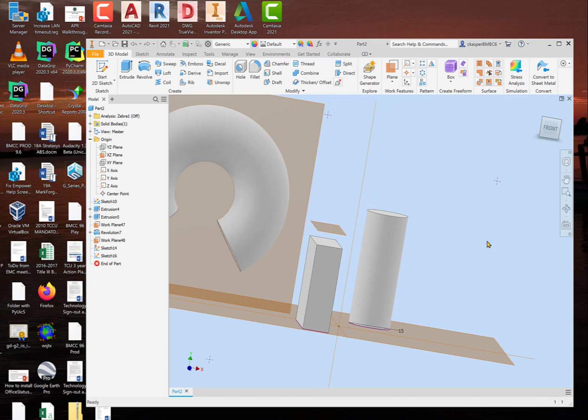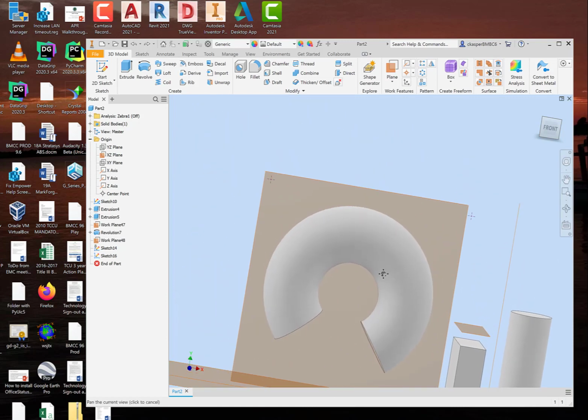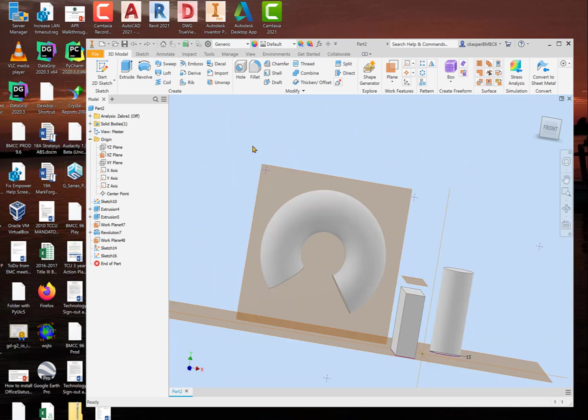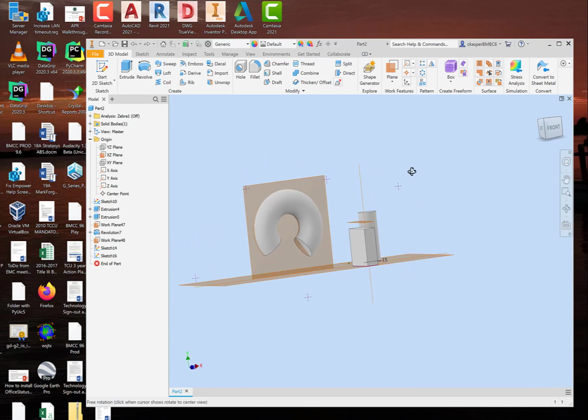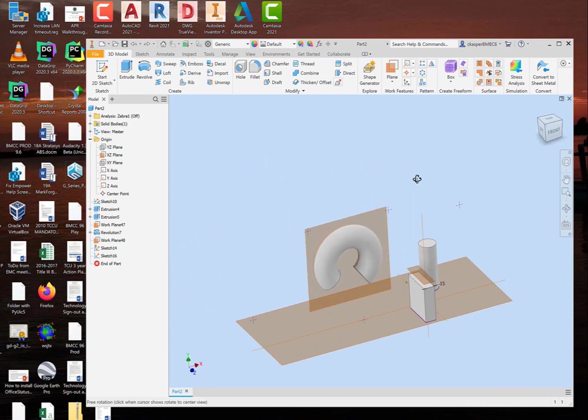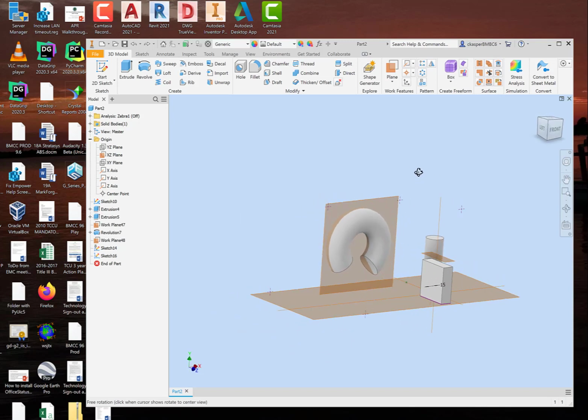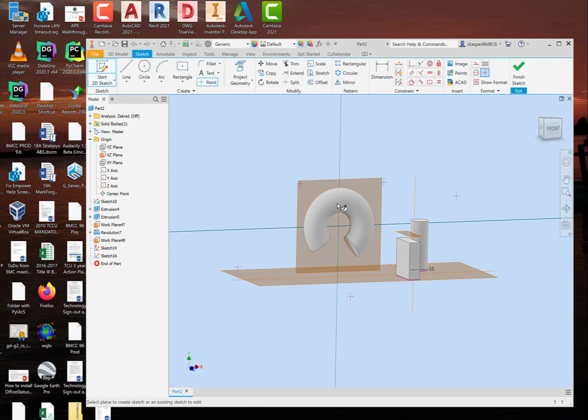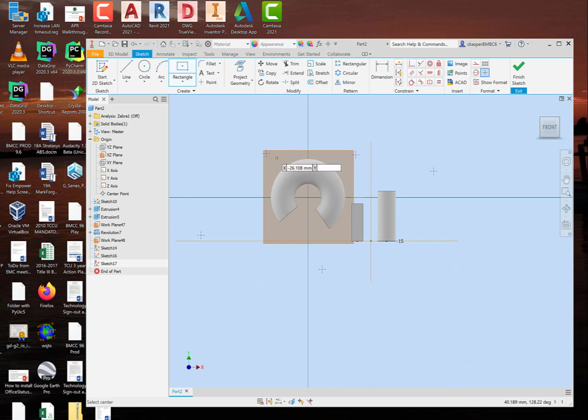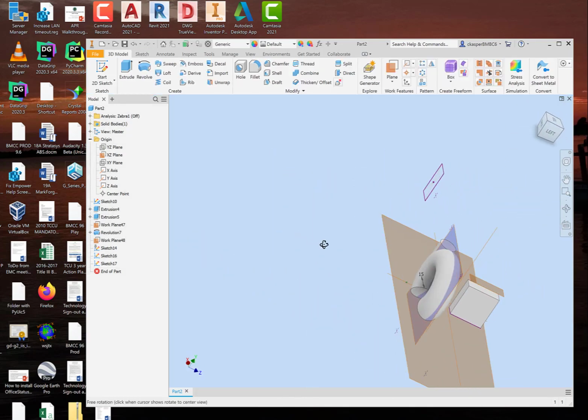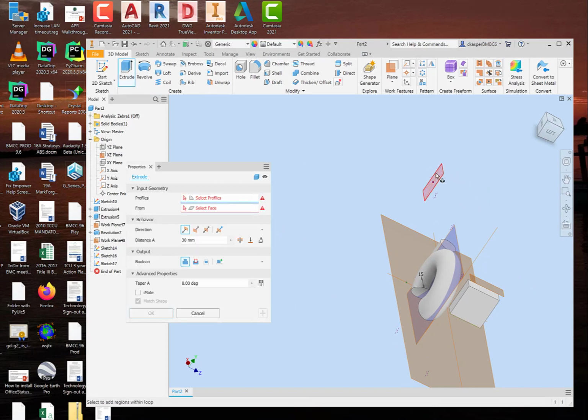What if I were to go to this? Yeah, let's do this. Let's see if we can draw another rectangle somewhere that has edges and draw through them. How about that idea? So we'll go to sketch. We'll sketch on that work plane again, put ourselves a little rectangle out here this time, and finish the sketch. And just because we're going to be fancy, we'll extrude it the other way. That way. 30 millimeters sounds like a win.